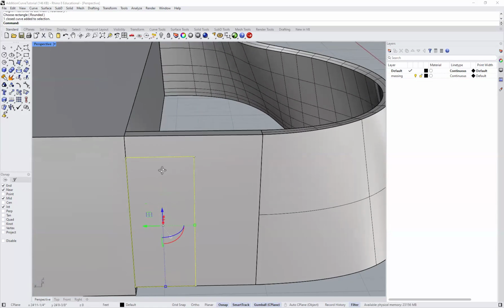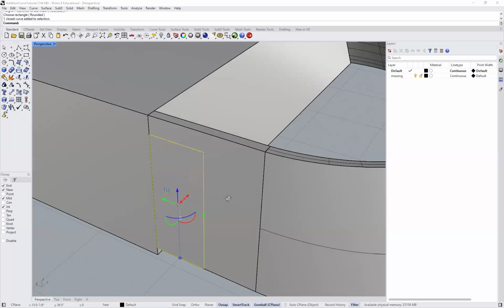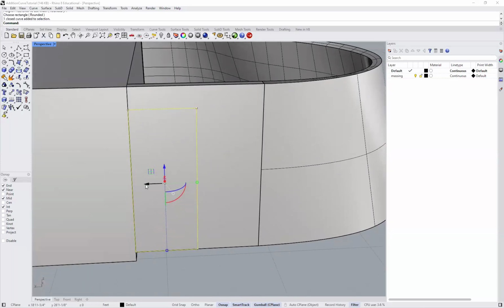Now I don't want it exactly flush to this wall. I'm going to want to move it to the right, maybe about 4 inches. So let's go and click there. Just type 4 inches. Oops, had to go in the opposite direction. So let's go. Well, now we have to go negative 8 inches. There we go.